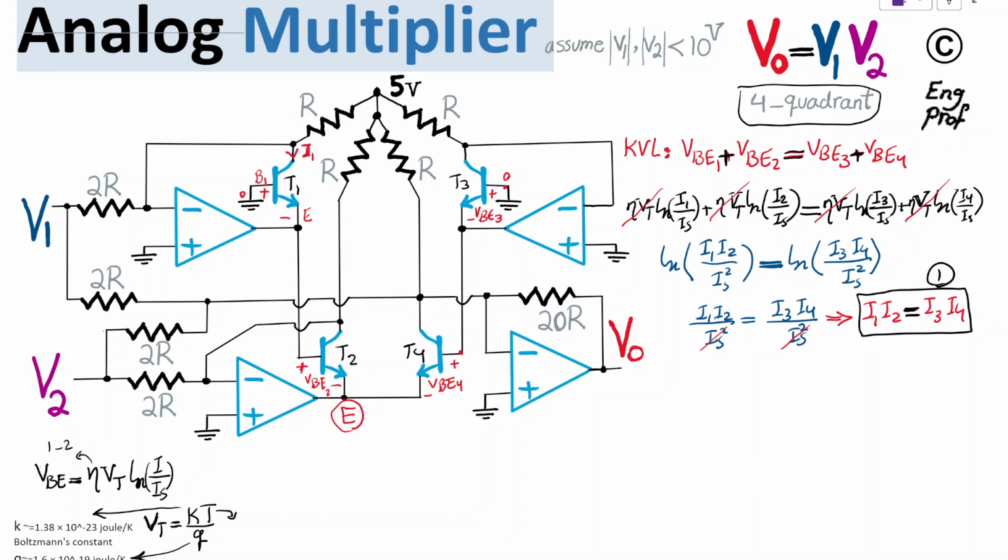And it's not hard to find, because if op-amp 1 is properly biased, with positive and negative supply voltages, let's say plus minus 10 volts, connected, so that the op-amp is operating in the linear region, then the virtual short is valid. It says that the voltage at the positive, non-inverting terminal of the op-amp should be equal to the voltage at the inverting, negative terminal.